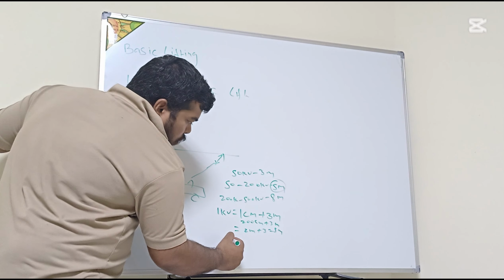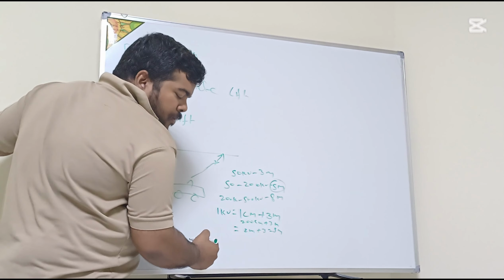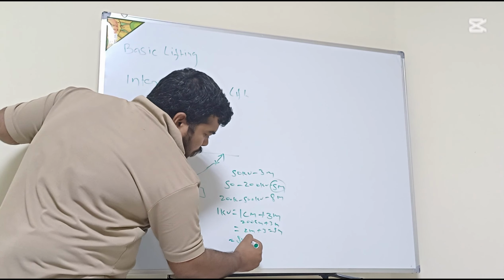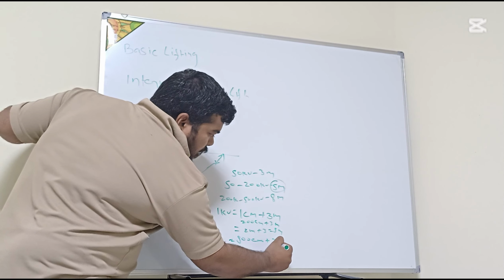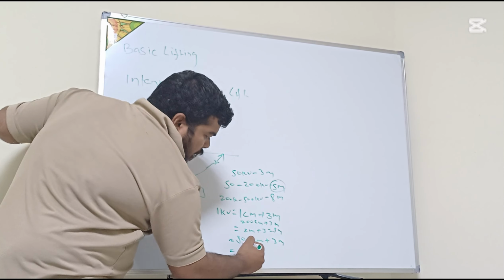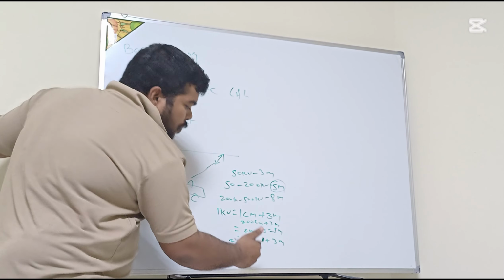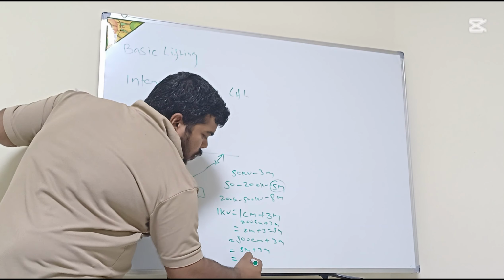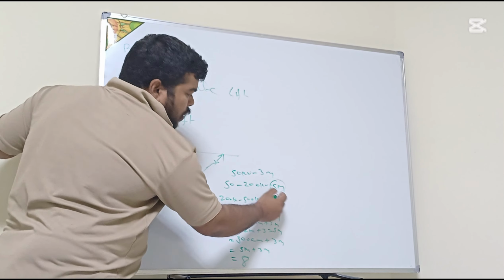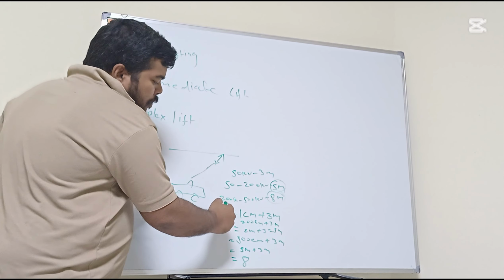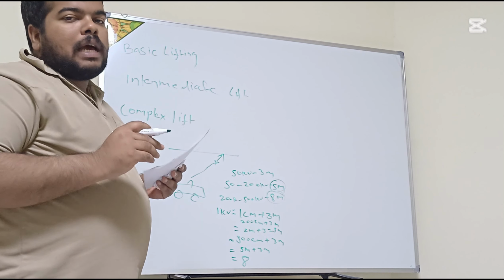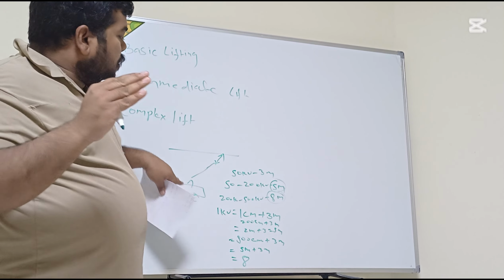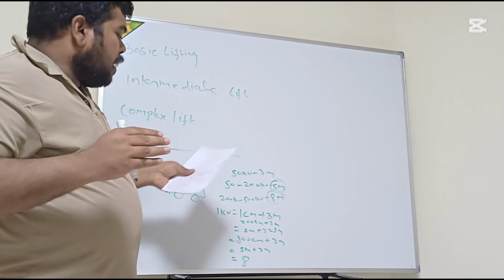Same, if you are going to calculate for 500 kilovolt, you get 500 centimeter plus 3 meter, divided by 100 if you convert centimeter into meter. So 5 meter plus 3 meter is equal to 8 meter. As you can see, 8 meter. This is just a simple formula for how we can calculate the minimum distance required when there is a crane operation nearby a live line.